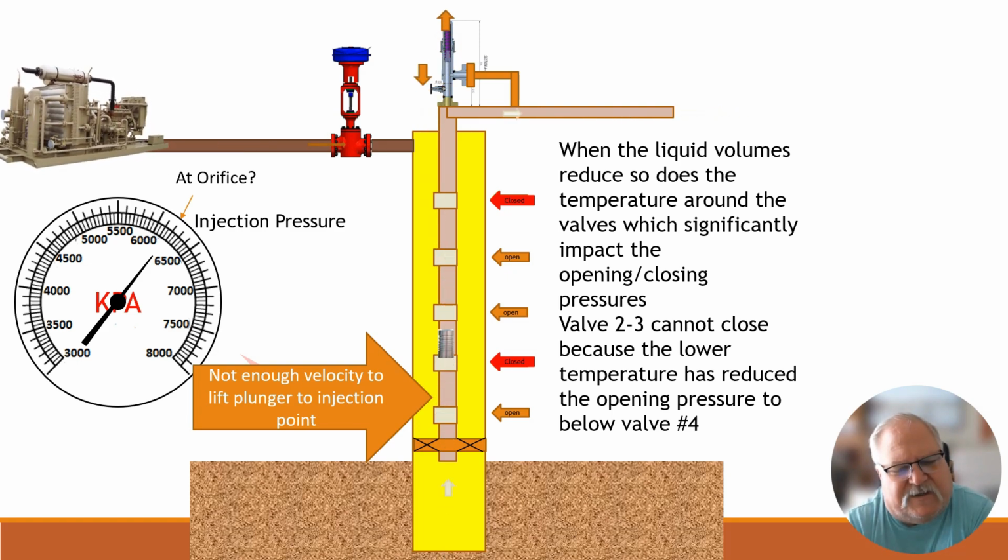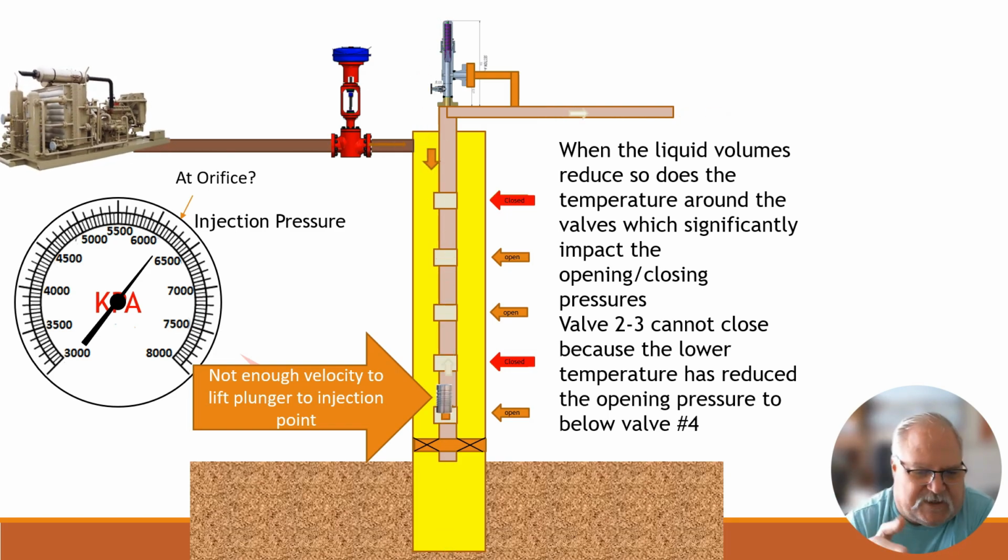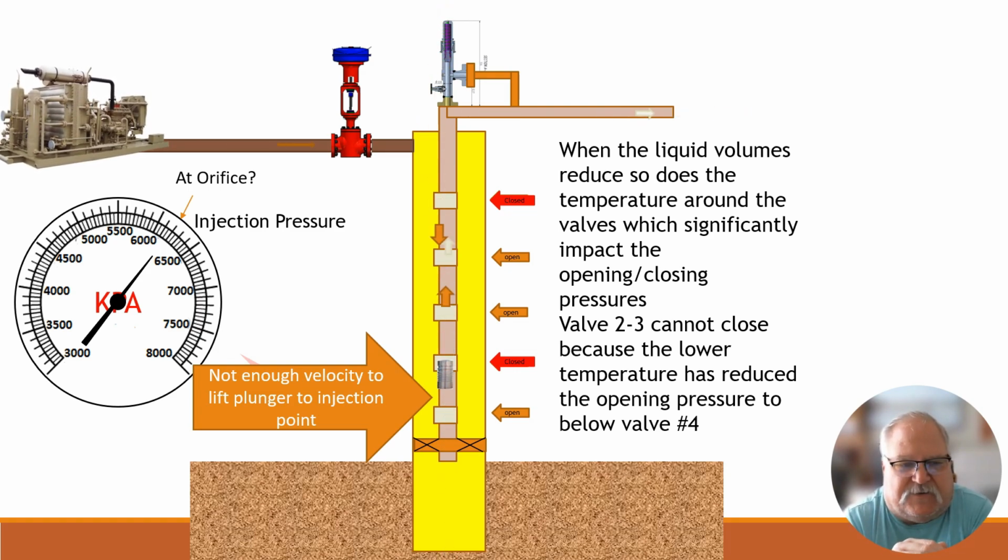And you got to walk away a little bit from this idea that you got to have the plunger up in 15 minutes or whatever the magic number is. Sometimes you got to accept that if we got a problem in the tubing and a bunch of the gas is being injected a little bit high, but the plunger is coming up every time, maybe you just got to accept that it's going to take 20 minutes and not 12, and don't keep cranking